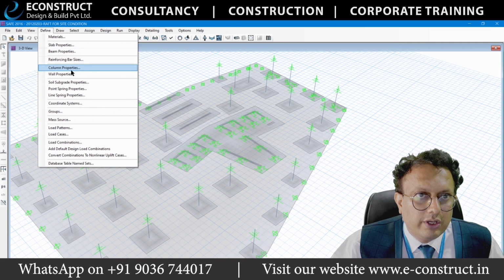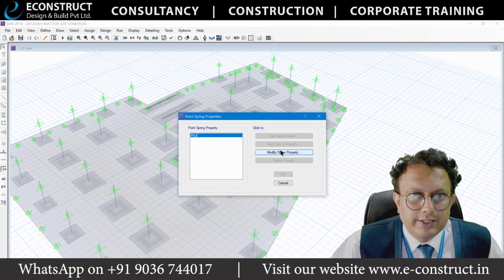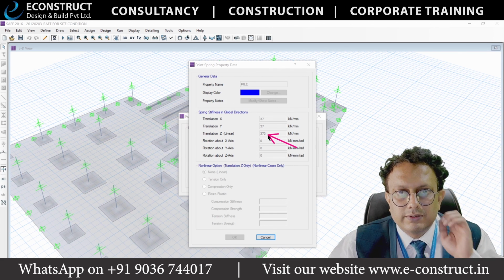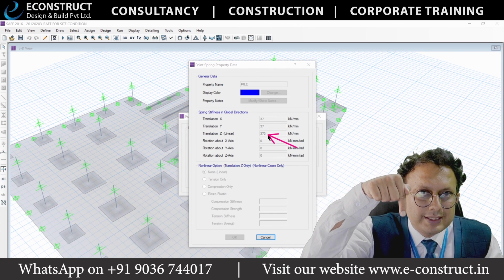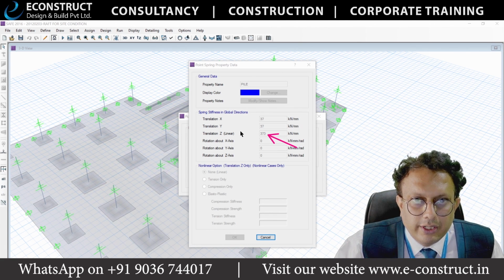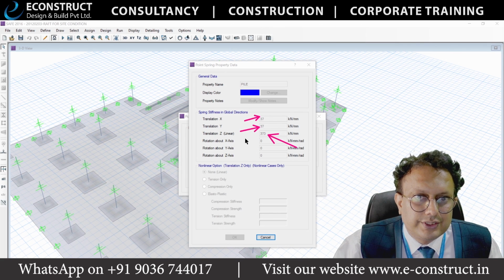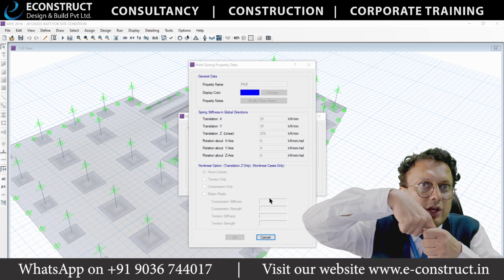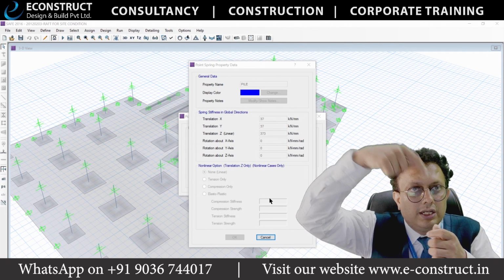Understood? So after the M30 grade of concrete is used, let's say for example, how to give the spring constants and all. You need to go to the point springs. So this is the spring constant. You will have this spring constant: the total capacity of the pile divided by the allowable settlement. And as I told you during the last session, this will generally be 10% of this. Initially you can go for linear, but later on you need to go for the compression only option. Understood? Why compression only option? Because piles will not work that effectively for tension.